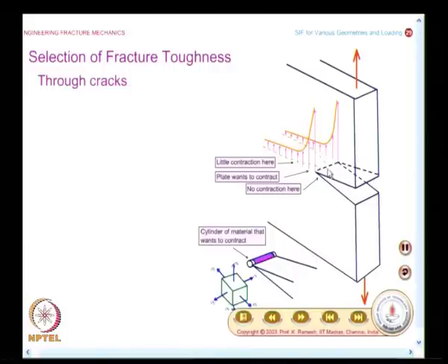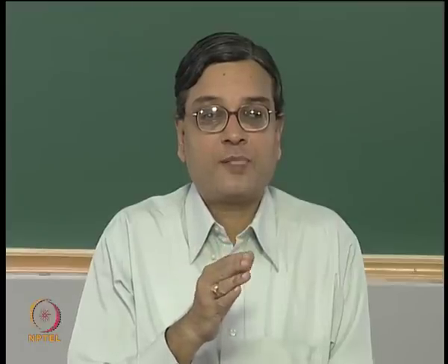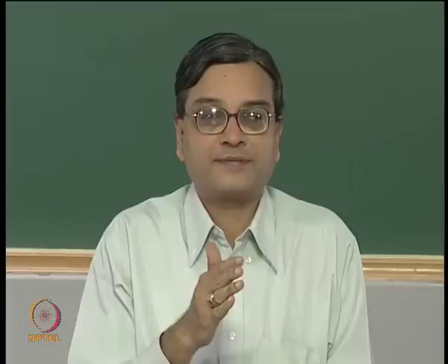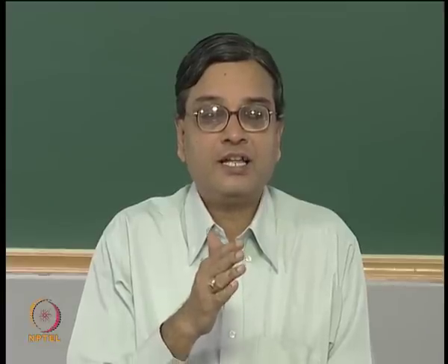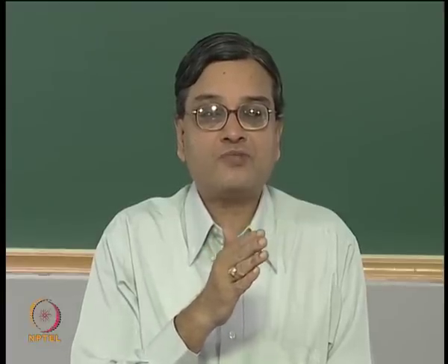What you can always notice is when you have a stress concentration zone, normally you come across a uniaxial field changing into biaxial field. But in the case of crack problems, for thick plates you have to also consider one more aspect. We have already seen when the crack tip is very sharp, sigma x equal to sigma y.